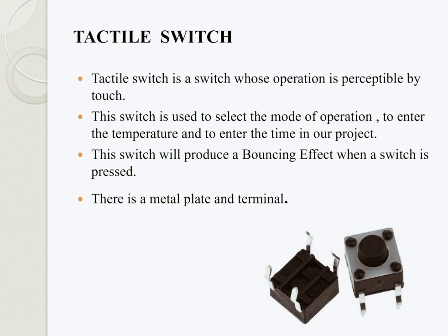Tactile switch. A tactile switch is a switch whose operation is perceptible by touch. This switch is used to select the mode of operation, to enter the temperature and to enter the time in our project. This switch will produce a bouncing effect when it is pressed. There is a metal plate and a terminal.